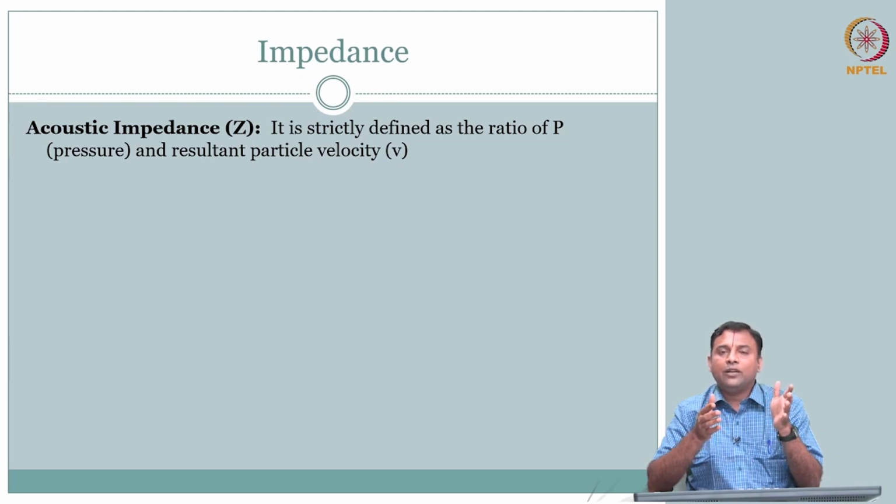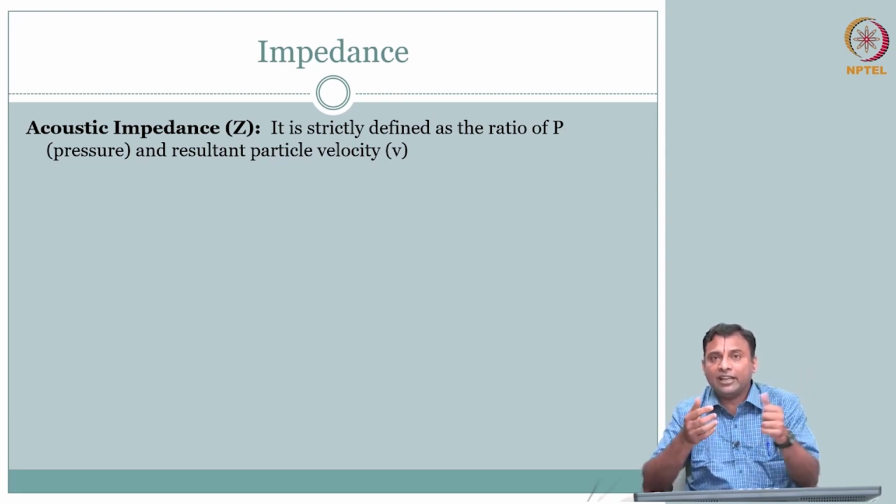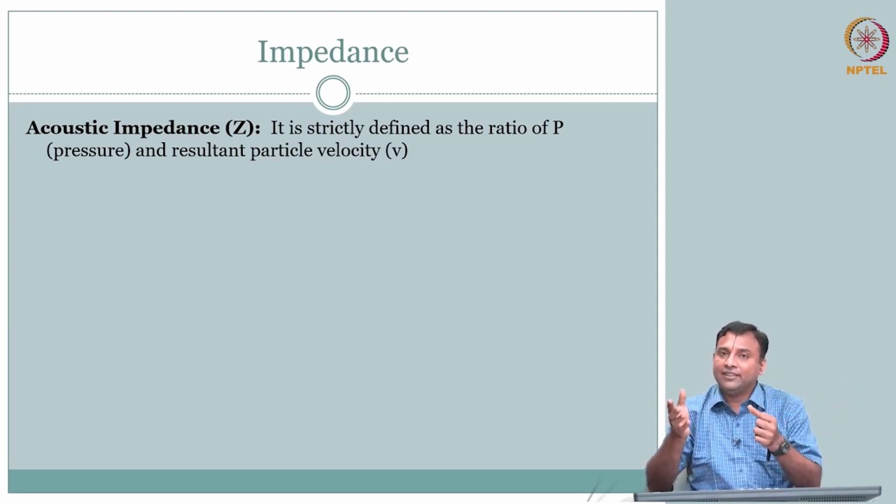So, impedance means, remember, it is analogous to your mechanical, analogous to the electrical system that you may be familiar with. Your pressure is the driver here. In electricals it will be voltage that is the driver, the voltage difference drives current. Here the pressure difference gives rise to velocity. So, the connection between V and I, the driver and what is flowing, is your resistance. If it is having frequency, you can talk about impedance.